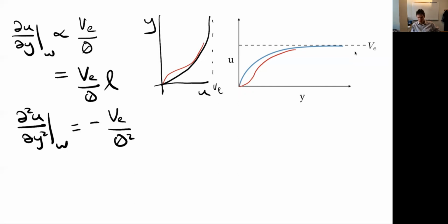And once this becomes flat, then the flow is separated. So an increasingly positive curvature is an indication that we're approaching separation, whereas the more negative the curvature is, like so, a steeper boundary layer, that's even healthier. I have even more velocity towards the wall. I'm even less likely to separate. So we can see already that this curvature parameter here is important in helping us to judge the health of our boundary layer or how close it is to separation.